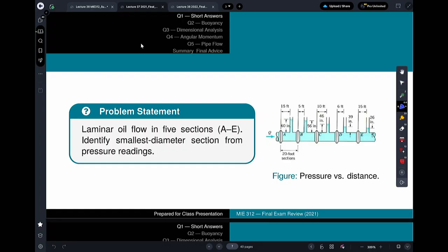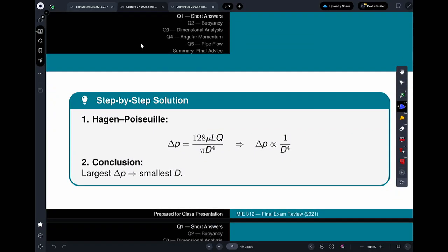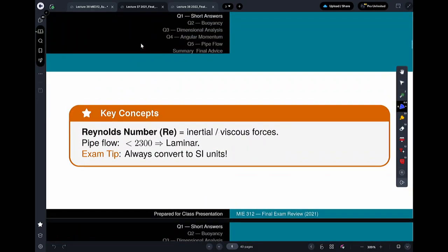So with a problem like this, make sure you know where you are, because you have a thing that's going 0 to 20 to 40, and so the third piezometer is 50 feet downstream. You should know all of that as you're looking at these problems. You have Hagen-Poiseuille, and you can calculate all of the terms. Did I forget the diameters?